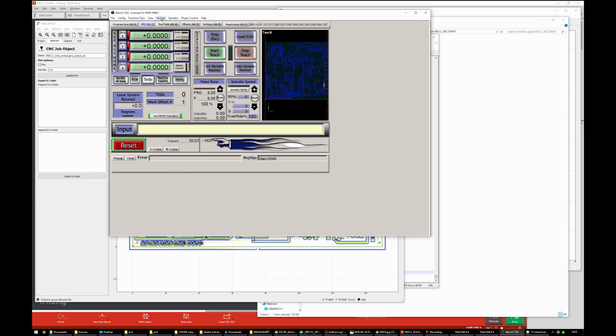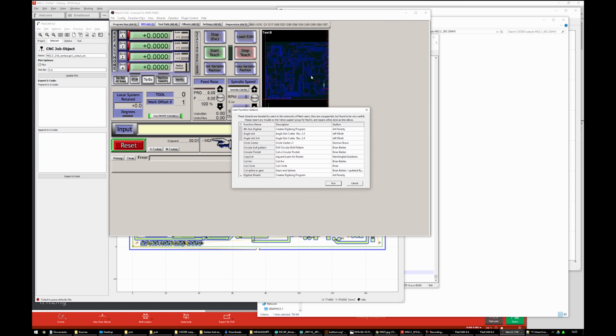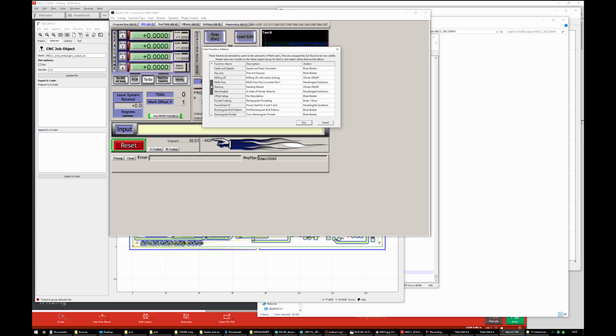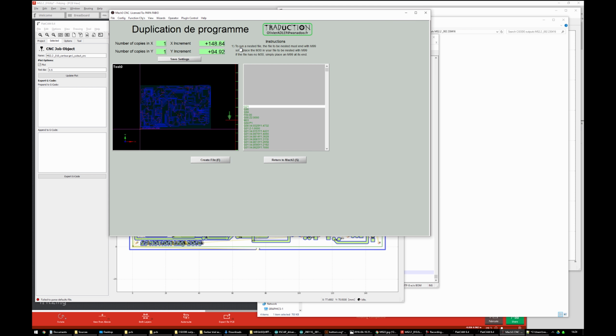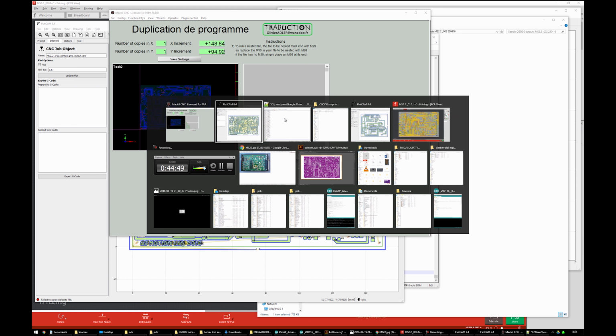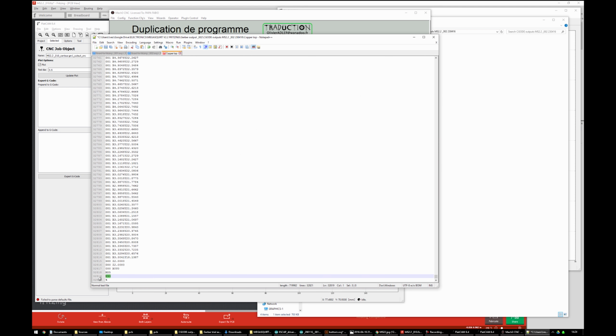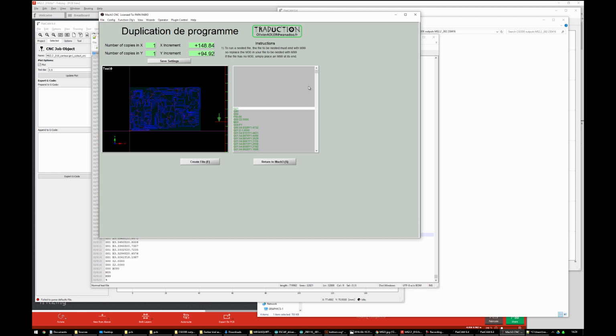Let's check out the nesting wizard. I'm not going to do this. I'm just kind of doing this for your benefit. If you want to do nesting, this instruction here says end with no M9. I replace M13. We don't have an M13 in our file, so we're good. Just put M99 and then we put a % sign. Let's try it. Eh?